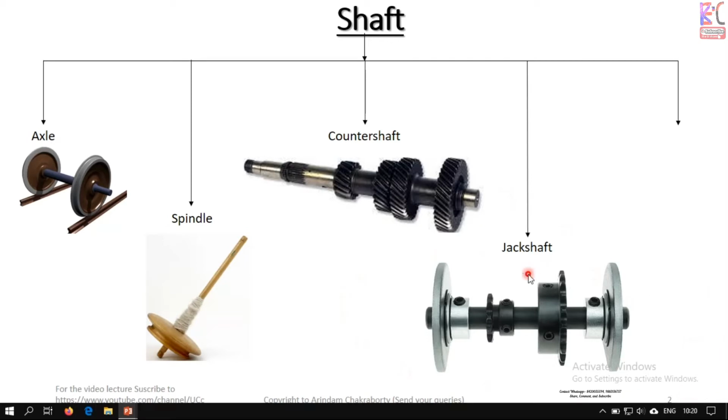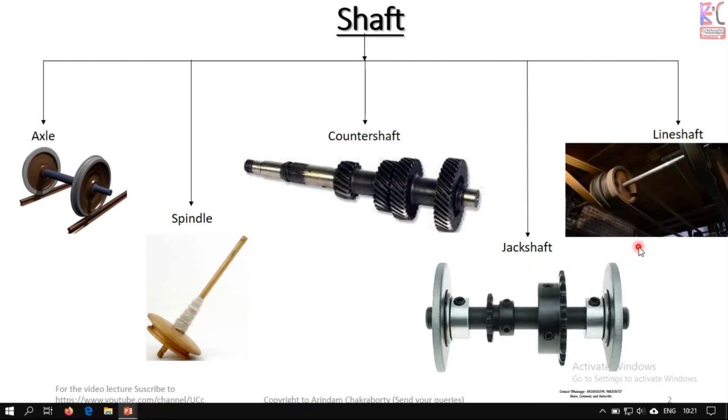Now this is a jack shaft, where two shafts are joined with couplings. They meet with coupling systems. Okay, the two shafts are made to work together. So this is called a jack shaft. And a line shaft is a shaft, as you can see, where a number of pulleys are there. So this will rotate and make a rotation of other components, and the components will receive motion from the pulleys attached to the shaft. So there will be a big, long shaft with a number of pulleys.